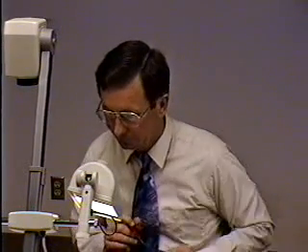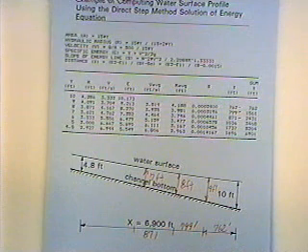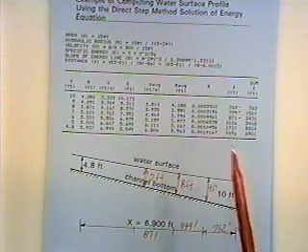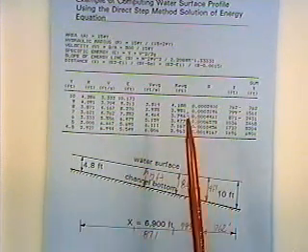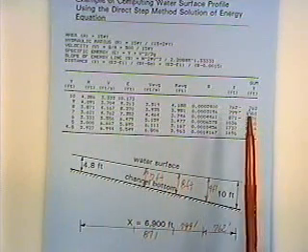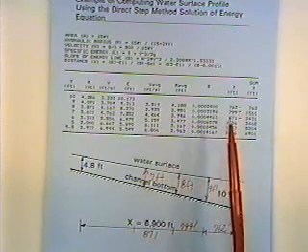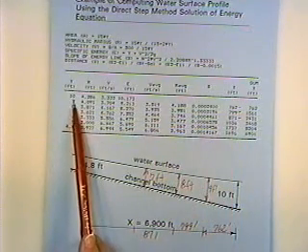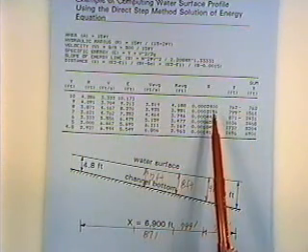One of the things that I did somewhat arbitrarily here is I used a delta Y, a step size, of 1 foot. And that was somewhat arbitrary, and recognize we used Manning's equation to get the S. We just plugged an average velocity and an average hydraulic radius into Manning's equation to get the slope term, the slope of the energy line. And so the smaller the step size, the less approximate is that simplification.